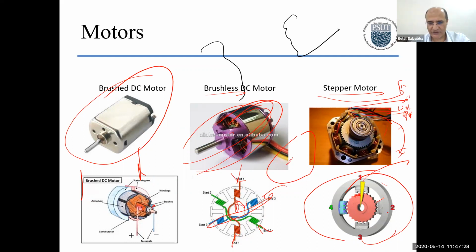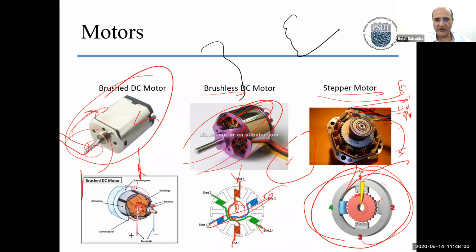Usually one of its characteristics also says that for a full cycle it takes, for example, 200 steps. So it's very precise, to make you move something you want to move. For a DC motor, there is no position control on it, right? For this DC motor, there is no feedback, so I can't know, for example, if I connect an arm to this, right? An arm. There is no feedback method to know how far this arm moved or how fast this motor turned.